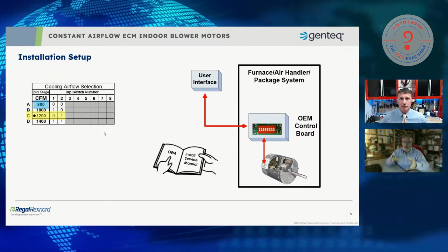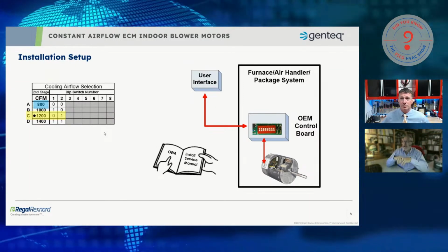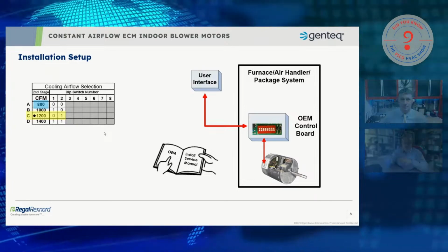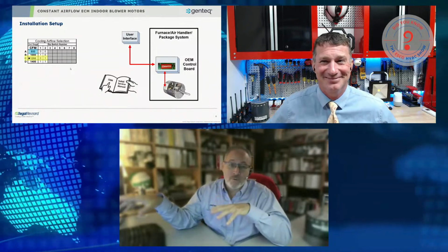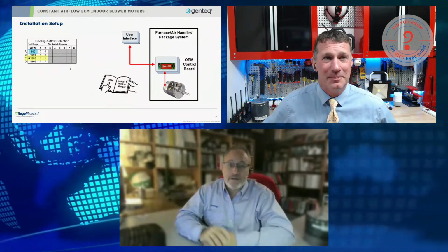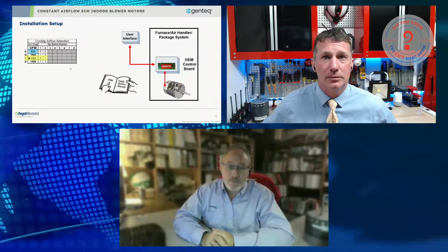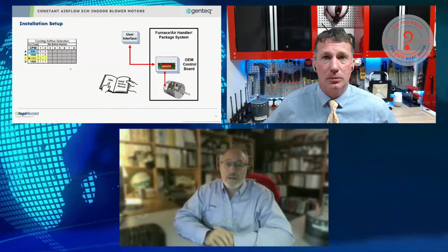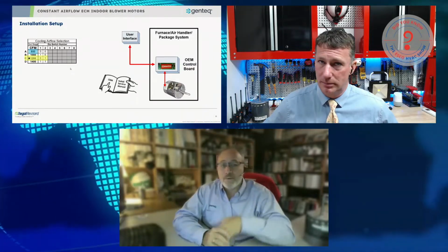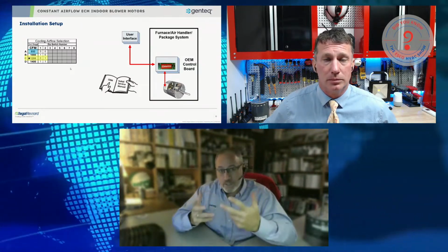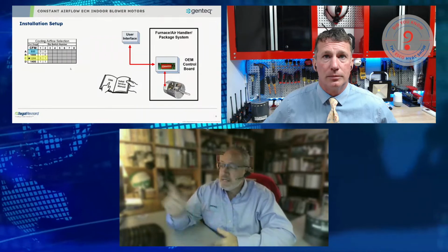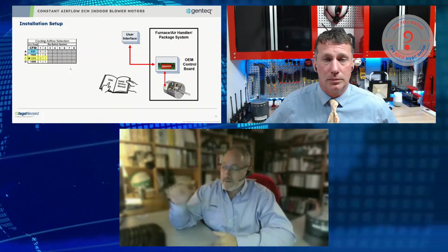And so here's your first real good laugh of the show, right? So assuming that house had perfect ductwork, insert laugh here. If it's only 2-ton worth of ductwork, so it's only 800 CFM sized ductwork, if it were perfect, that motor is going to try and push 1200 CFM through it. So it's going to be working harder. We talked about that in that thermistor failure. It's an implication of the motor working hard.